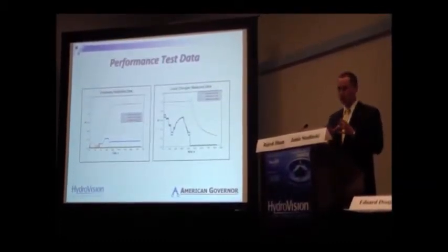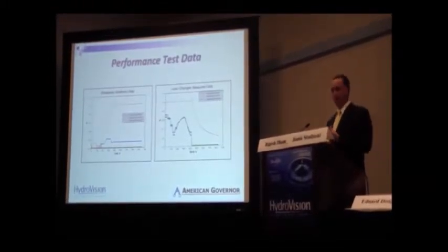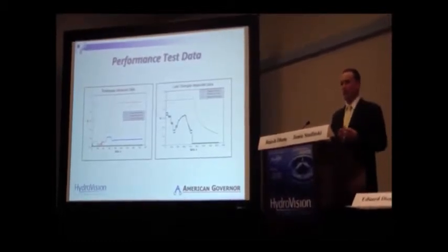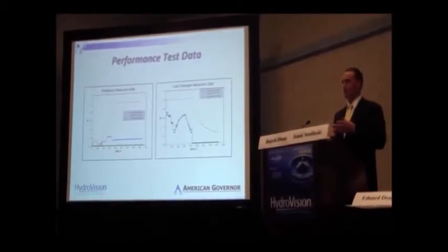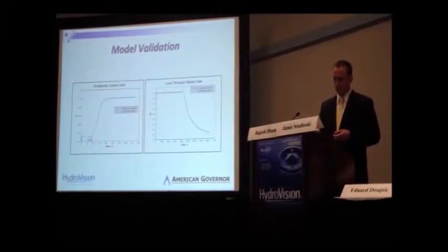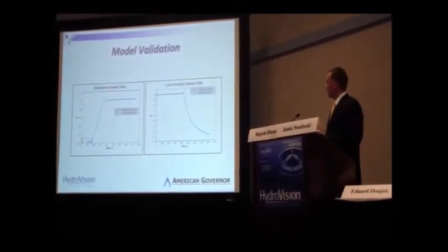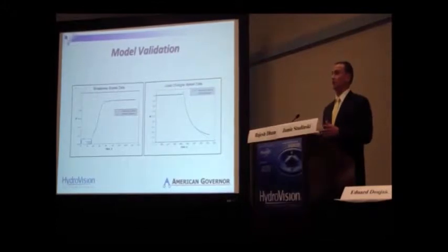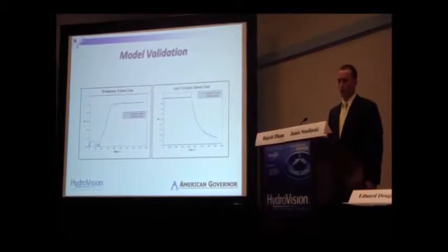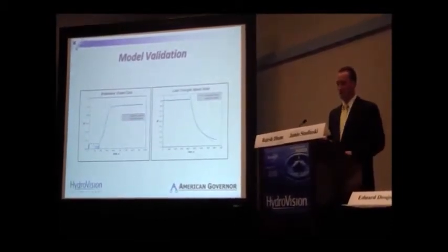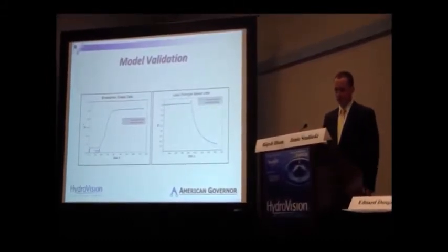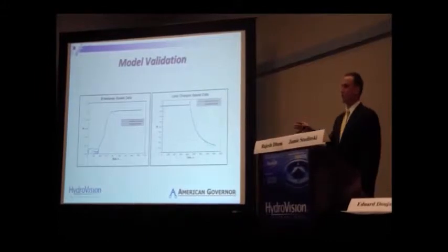So we have our skeleton of a model, essentially, with all of this plant data. And what we then had to do was run a regression technique in order to take that data and sort of mold and shape the theoretical model and turn it into the Castaic power plant. And after we've done that, we ran through a cost minimization function. This is an optimization routine we ran in that numerical tool. Essentially, it's a 13-dimensional optimization problem because it's accounting for all of those coefficients and all those things which have yet to be defined. But we can see what we get after we run through this numerical routine.